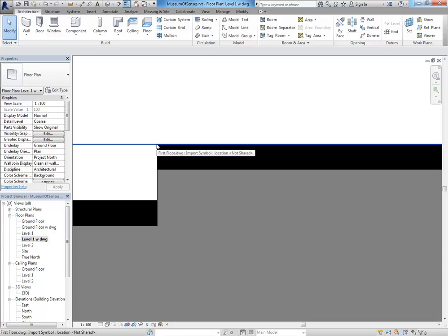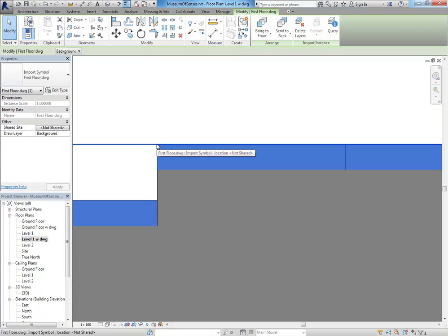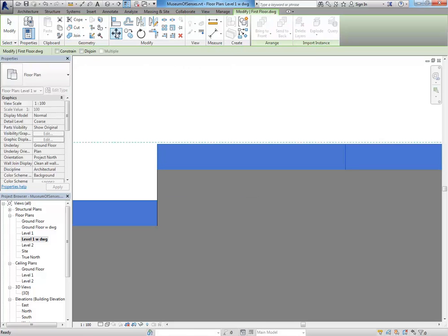And so with my AutoCAD drawing selected, I just wanted to go over the move command because this is one that you can easily skip over. So I've selected the drawing, and now I'm going to click the move button. So rather than just trying to drag this thing, if you click the move button, then you can give a base point, and so I'll pick it up on the corner there by snapping exactly to that endpoint, and then I can snap to the corner of my wall.